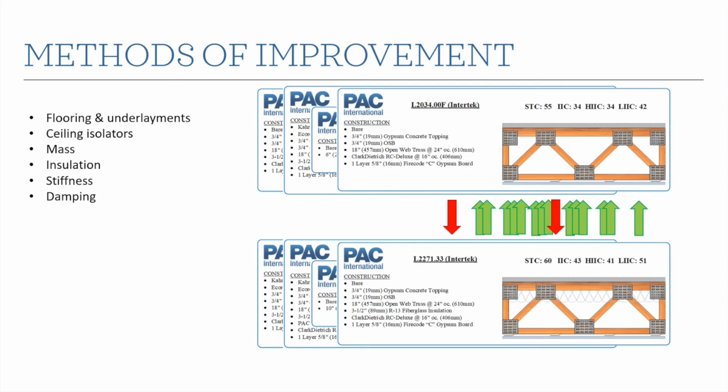That's very important. And a lot of times our designs for fire are dictated by UL fire-rated, fire-resistive designs, right? And a lot of those say that if you increase the insulation thickness above 3.5 inches, you have to change your channel spacing and you have to reduce your channel spacing. So increasing the insulation thickness might improve your acoustics, but you have to reduce your channel spacing, which might reduce your acoustical performance. Or if you forget to change your channel spacing, you may have an assembly that's actually no longer fire rated, and that would be a very bad situation.